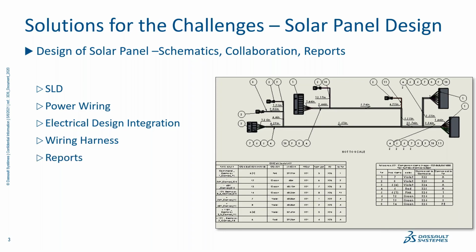After the wiring harness is carried out, the next thing is to generate the form board drawings or the flattened route for the same. So the tool must also help us in generating the flattened drawings. SolidWorks Electrical provides the interface to generate the flattened drawings and create a harness from that.